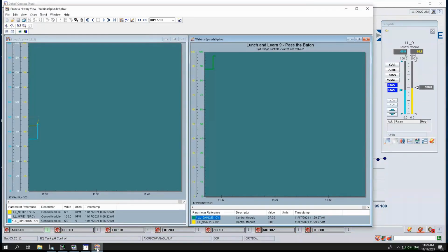We're going to flatten out on our flow characteristic. Now I'm going to go to 50%, which is kind of no man's land. And obviously, valve 1 goes to 100% flow. We're getting very little flow change here because we lost all our modulating capabilities.